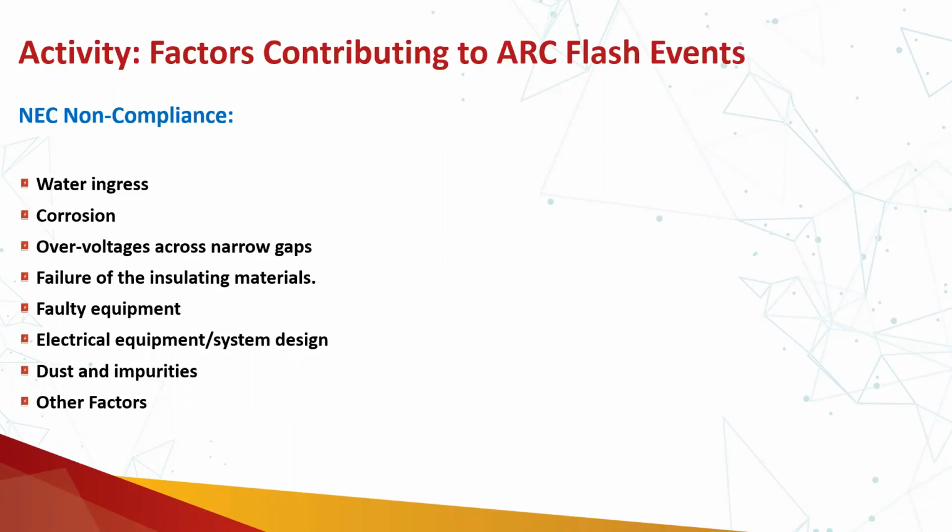So it was the wrong selection of the material, which has resulted in that incident. Or electrical equipment system design issue, dust and impurities, again due to IP rating issues and other factors like rodents have entered into the electrical equipment. Why were there openings there?